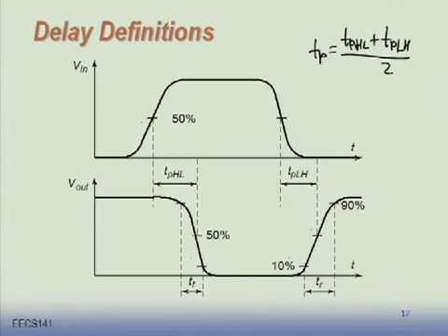Yeah, exactly. So when somebody asks you, what is the propagation delay of an inverter in this process? Oh, TPHL is this, TPLH is that. People would like to say, I give you one number, the average. Although it's not something physical. But in practice, when you're timing a path that has inverting gates, you're going to see approximately that.